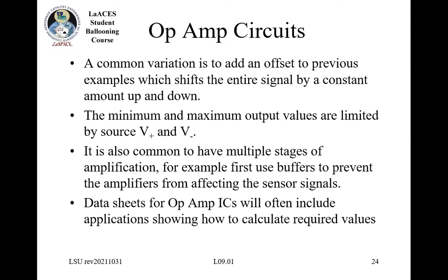So often you'll see one op amp feed into a second op amp. And like I said, if you're trying to figure out what values you need for a resistance, you want to look at the data sheets, or most manufacturers will have some sort of design document that will step you through how to pick the values for the resistance to get the actual amplification you're looking for.